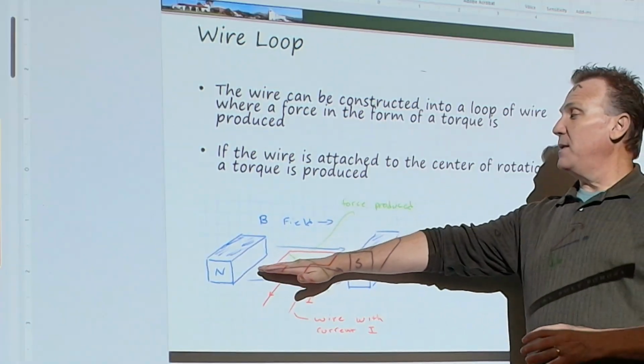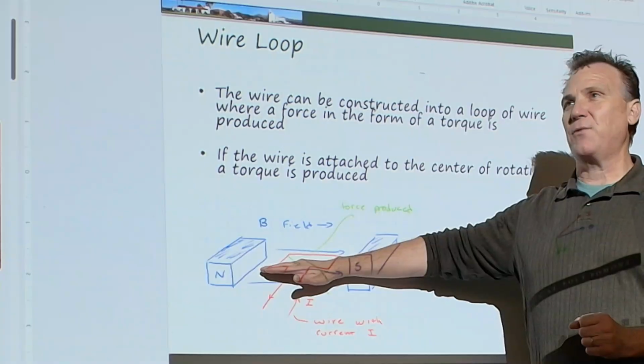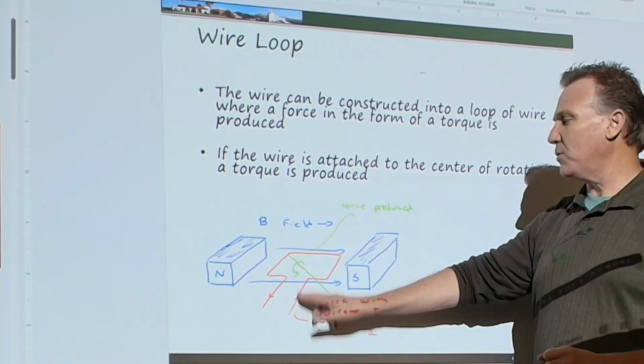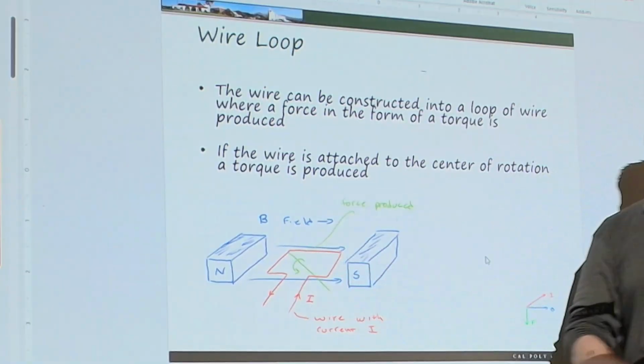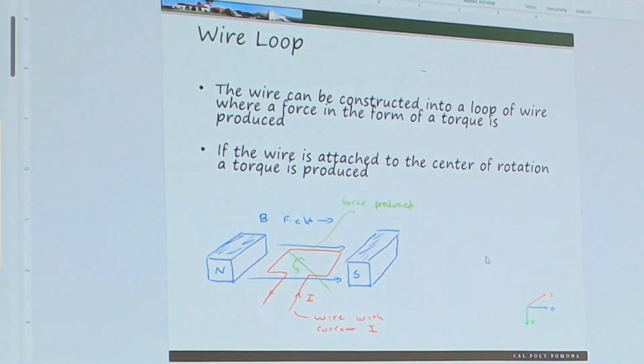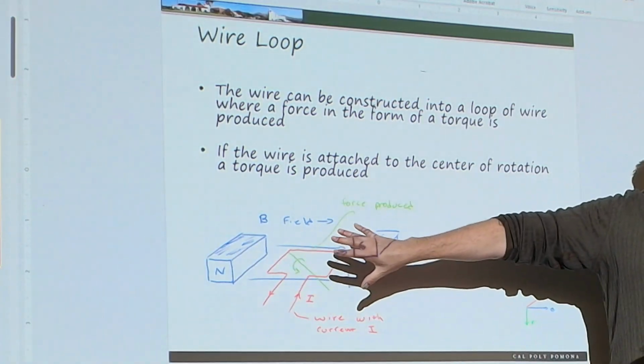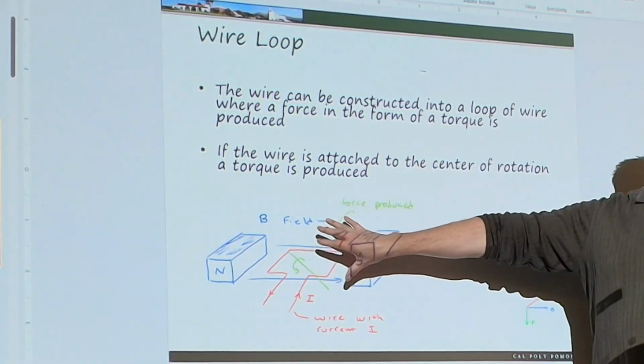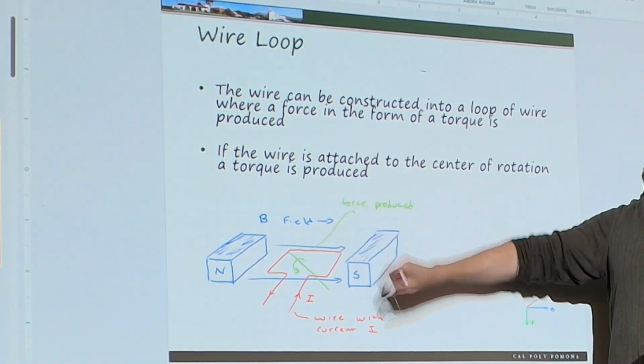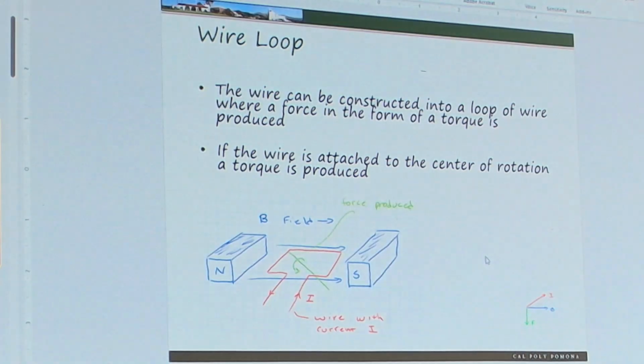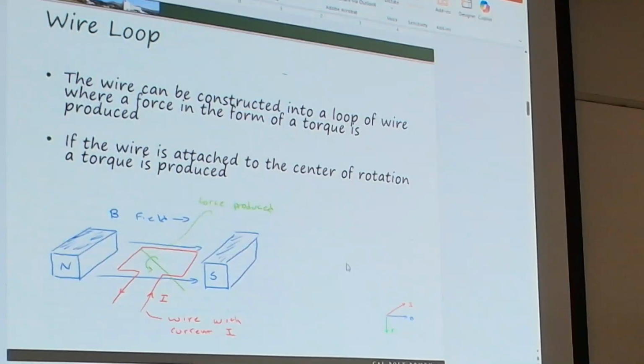If this is not allowed to move, for whatever reason, and I'm applying current, then what happens to the energy if the energy can't be dissipated through force? It generates heat, because energy can't be destroyed or created, just transformed. We're not going to use it as mechanical; it becomes thermal. The power of that will be I squared R. I'm getting a little bit ahead of myself, and I don't have quite this in the slide, so we're just going to talk about it more abstractly.